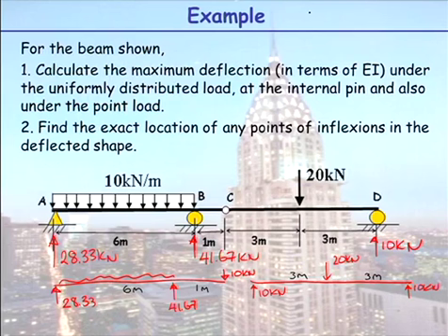And when you split it in two halves, as I have drawn here in red, you then have to ask yourself, which half can I start? Where can I start? So the right-hand side does look simpler. However, if you attempt to get your boundary conditions here, if we consider X to start here when you look at the right-hand side, and X to start here when you look at the left-hand side, over on the right-hand side, you would say, okay, well, when X is equal to 6 metres, that's at point D.